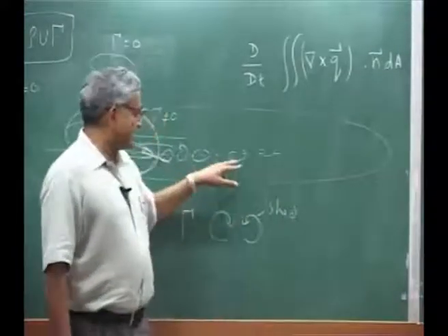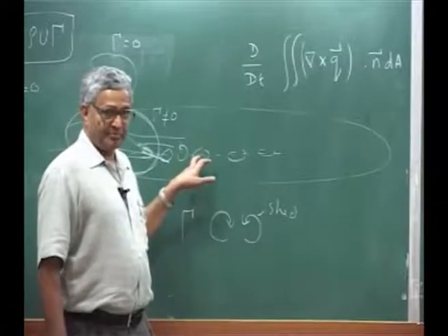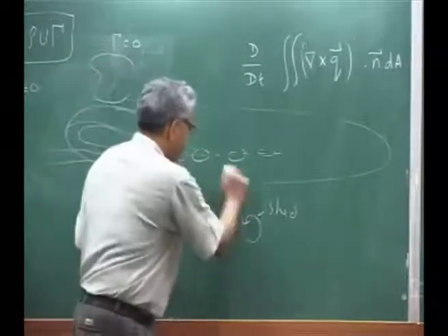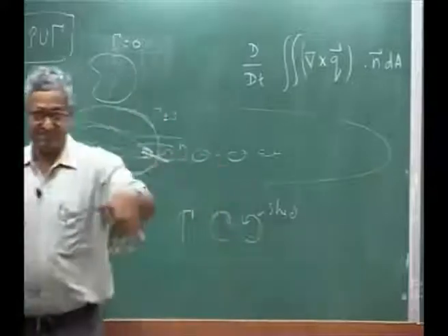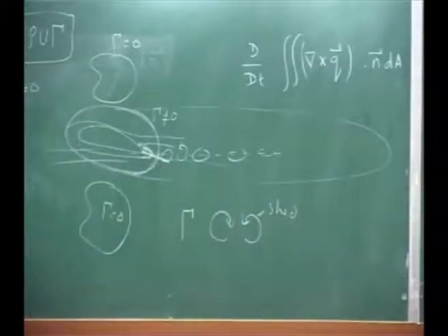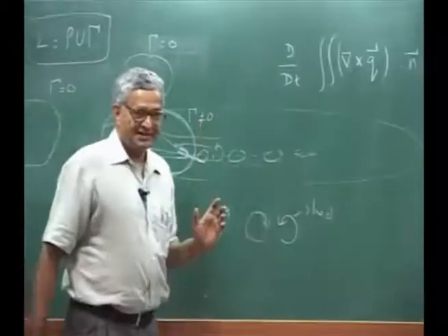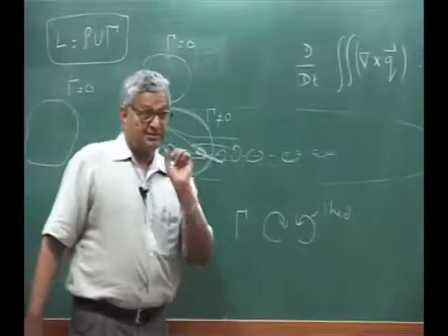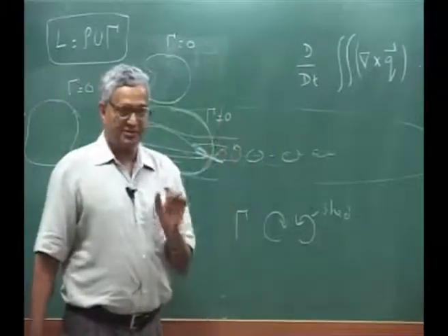And there is no interaction between this and this, because this and this may turn it this way. The structure can change. Okay, that is why those are all complex theories. We will not get into that. We will use that there is no interaction between these vortices. That is like a prescribed wake. This is what is called a prescribed wake.